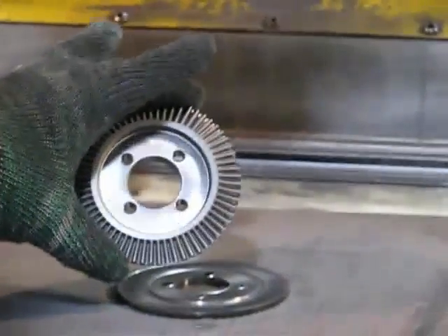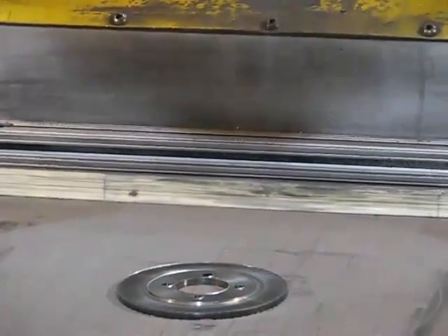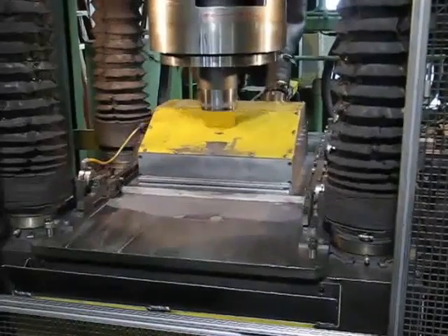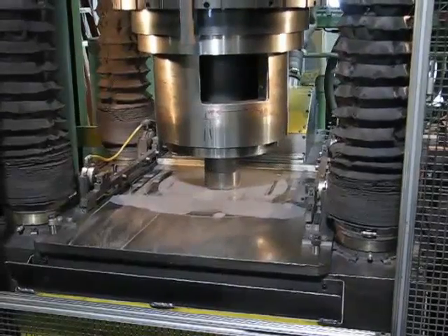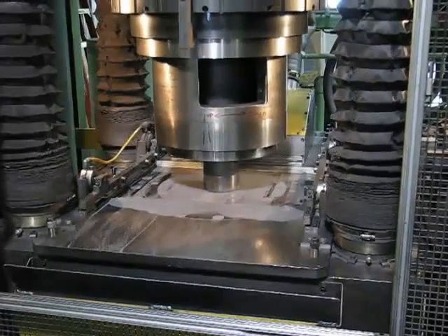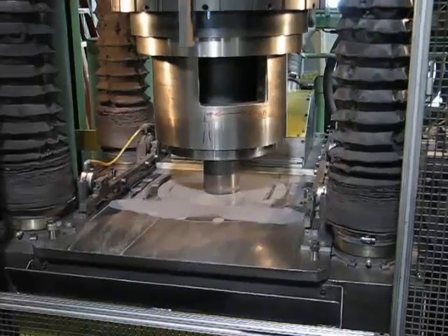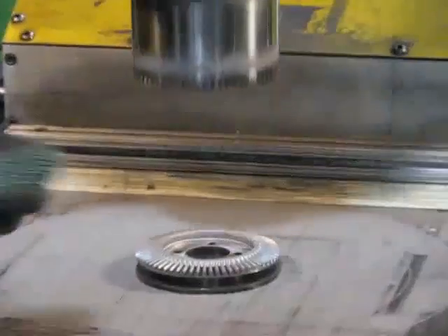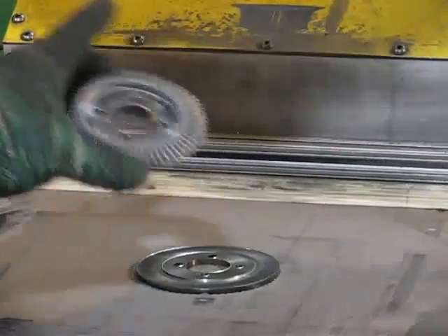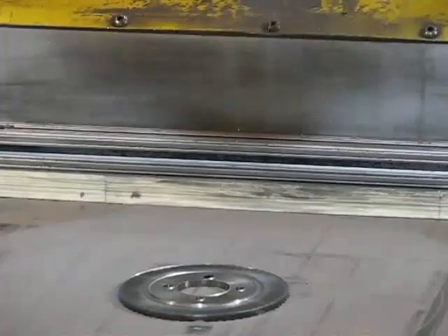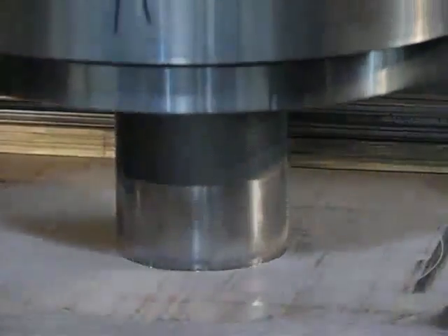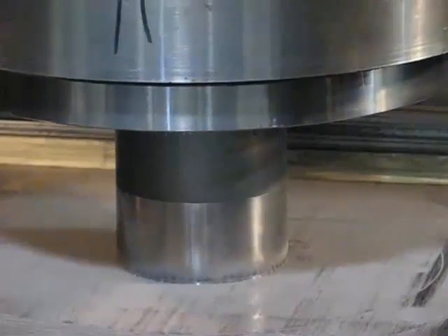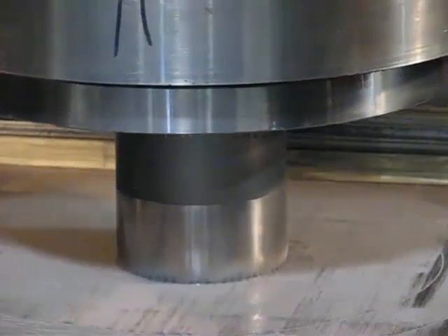In powdered metal, one of the ways that we calculate how large of a press we need, and ultimately how big of a part we can make for you, our customer, is by surface area. It is the single largest surface area, excluding any holes that go the entire way through. So in this case, the 4 bolt holes and the large central hole are not included in tonnage to compact. That part takes right around 300 tons to compact at the density required. In this case, that is an iron nickel alloy that is subsequently heat treated to create a very hard particle hardness.